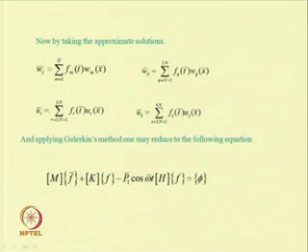Now, taking W t in this form, we take a few modes of the system. As this is a continuous system, one can have infinite degrees of freedom, but for analysis purposes we can truncate the system to a few finite degrees of freedom. Let us take the first n degrees of freedom of the system. By taking the first n modes, we can write W t bar equal to summation m equal to 1 to n of Fm t bar Wm x bar. Here Fm is the time modulation and Wm is the shape function of the system. The shape functions depend on the boundary conditions, so we can study the system for different boundary conditions. Similarly, W b bar can be written.